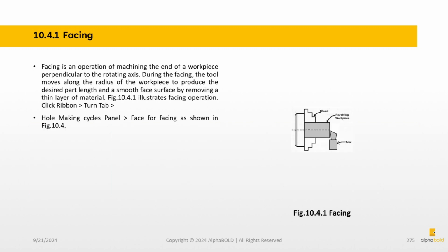Facing is an operation of machining the end of a workpiece perpendicular to the rotating axis. During the facing, the tool moves along the radius of the workpiece to produce the desired part length and a smooth face surface by removing a thin layer of material.